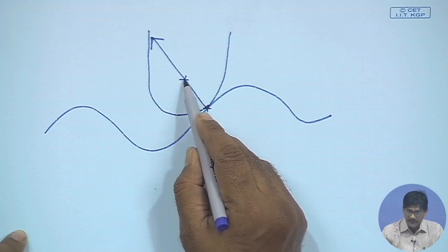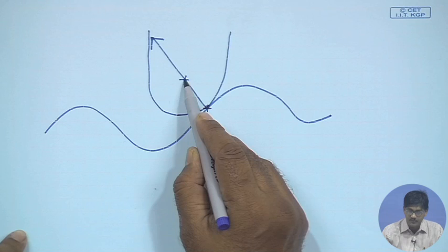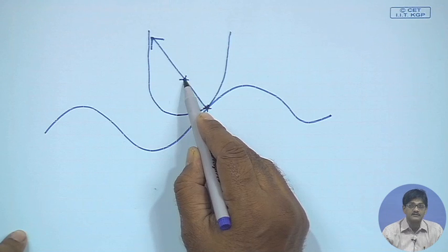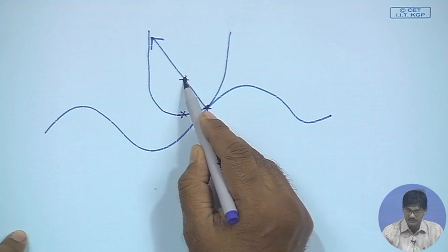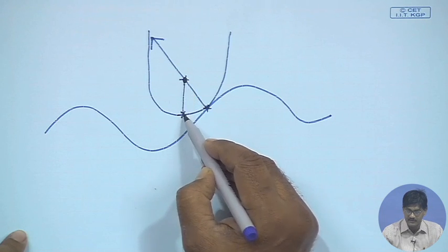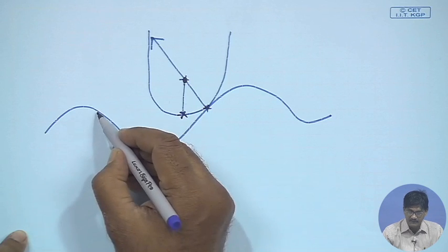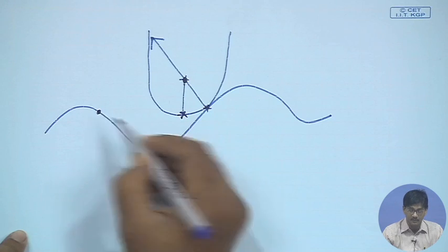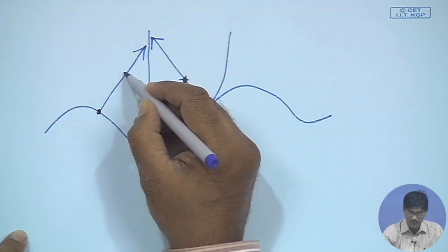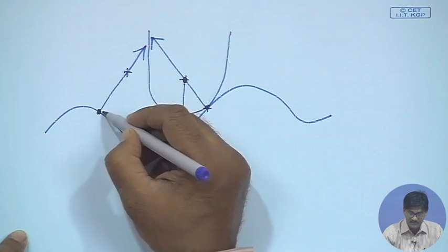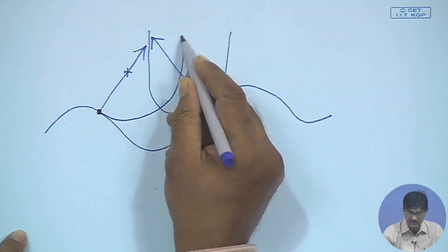So, I can find out this is a fixed point on the cutter. Once I know this, the cutter is defined in position. I could have given this point also. This point is just a move along the z axis by radius, you will get this point. So, if I have this point as the cutter contact point, I can draw the normal, I can move by the radius, and say this is the center of the spherical end of the cutter, this is the cutter position.